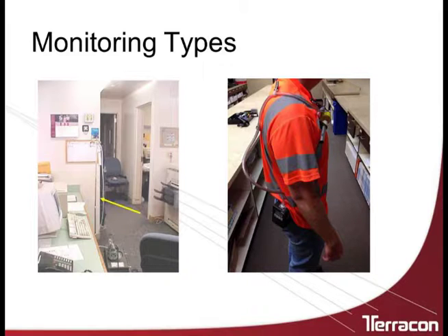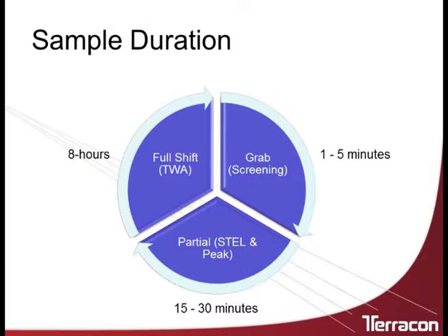One of the things you also have to take into consideration with respect to sampling is the sample duration. If you look off here to the left, grab sampling, typically, is something where you're trying to get an idea what you might be dealing with. You just want a quick and dirty way of trying to get an idea of what the material is, or you can also use that for the purposes of determining whether or not you have a noise hazard.